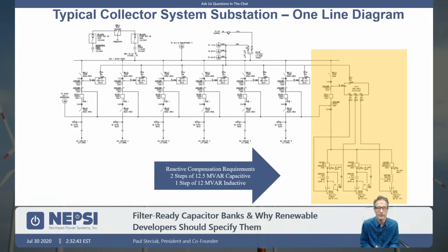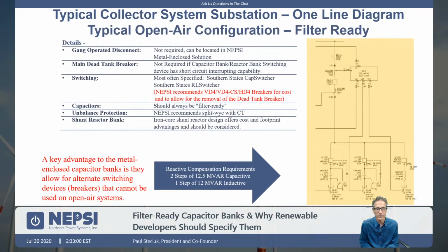And remember that oftentimes renewables have to install shunt reactor banks for light load conditions to consume VARs to possibly bring down the voltage within the collector system during light power output conditions. So we detail out everything that's necessary to install this system.